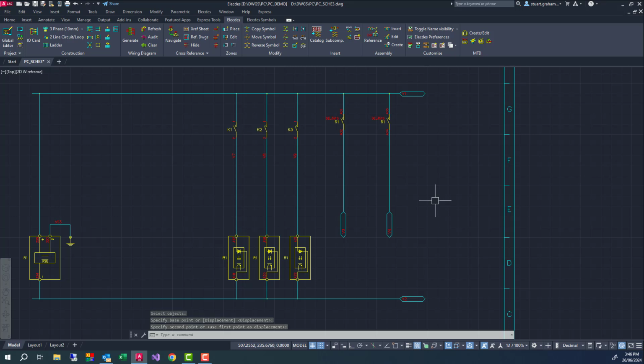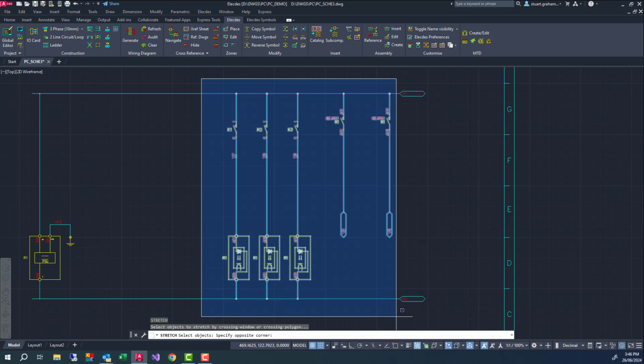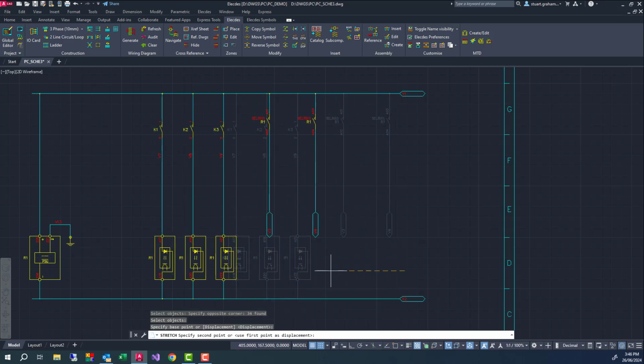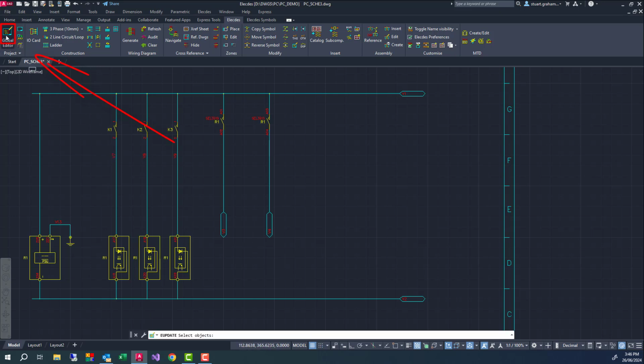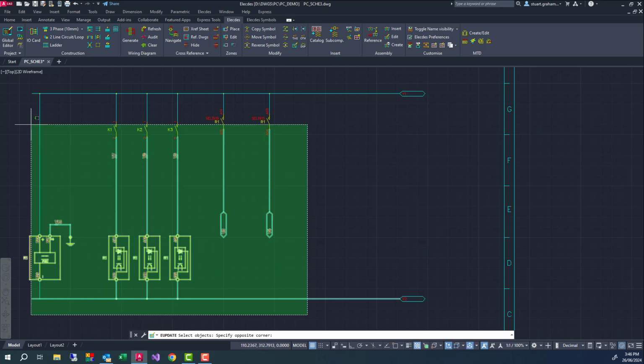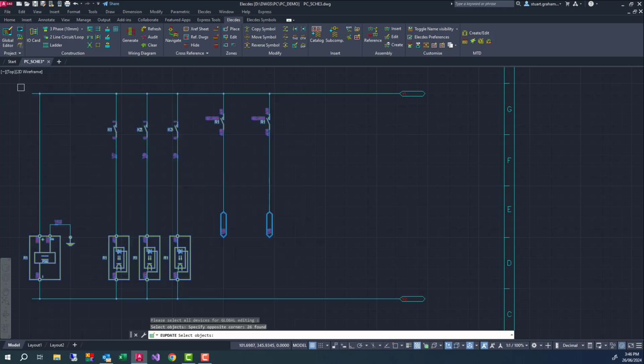Within the global editor, the components are segregated by type. There is a table for devices, cables, wires, terminals, and several other table types. The global editor can be used to edit components on a section of a drawing, on a whole drawing, or any number of drawings from your project. I'll start the global editor and global edit my third sheet in its entirety. I'll ensure I have not duplicated tag names.